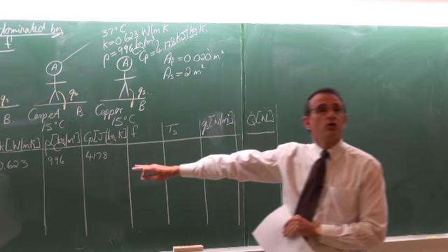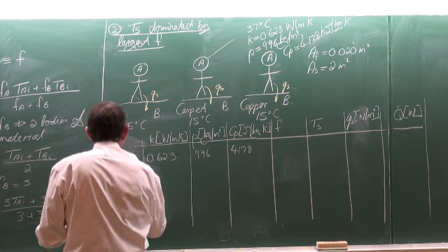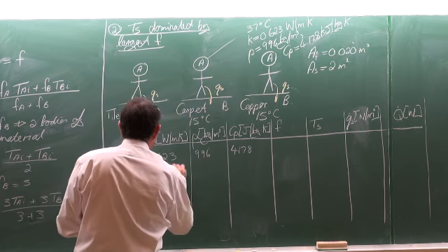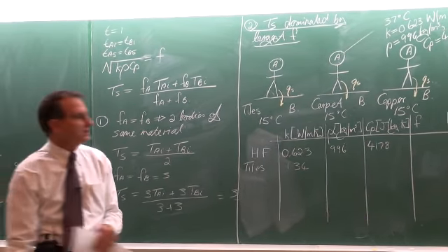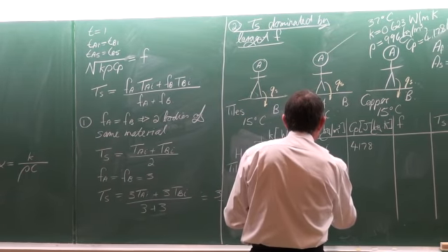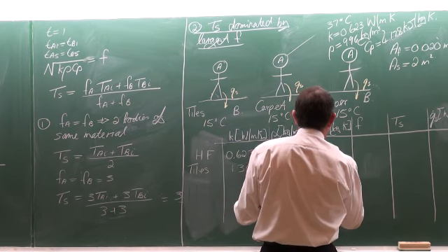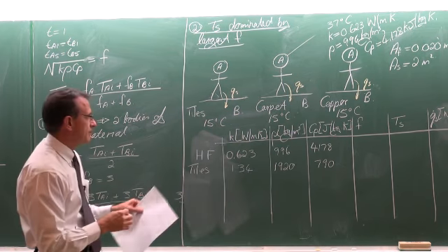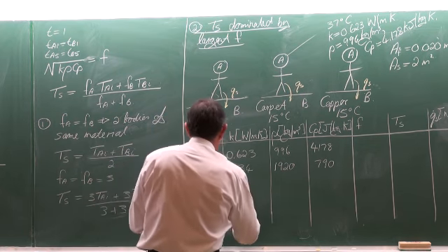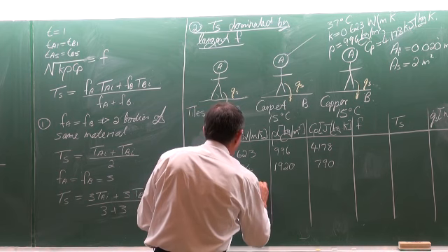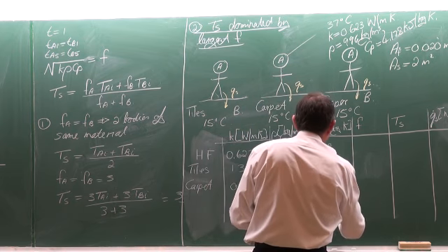Okay, so those are the properties for human flesh. The properties for the tiles, if you go and look in your textbook, you'll see the thermal conductivity of tiles is equal to 1.34, which is very close to that of cement, 1.34. The density, 1920. The Cp value, 790. Then for a carpet, it is equal to 0.039, 1121, and 1420.